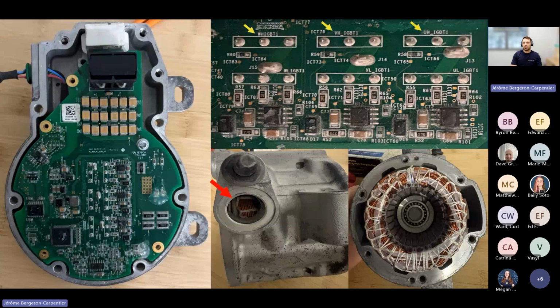So that's our high voltage AC compressor, which is one of the most important components in a heat pump. That high voltage AC compressor basically is a brushless DC motor. So we do have an inverter that's going to convert the high voltage DC to a three-phase motor.